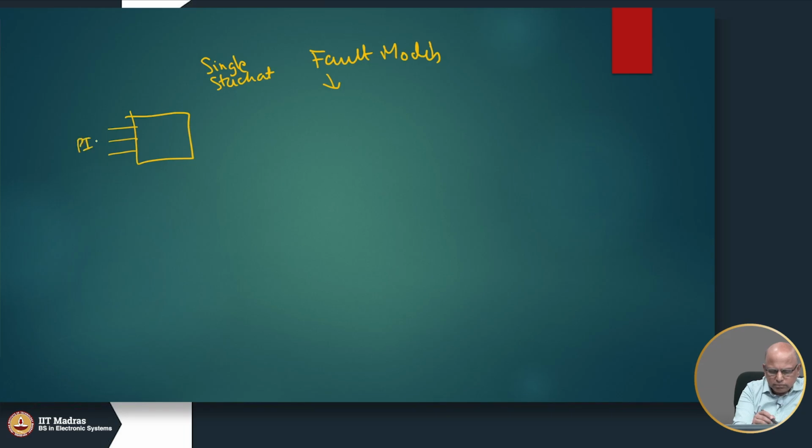So, we have been talking about fault models. In particular, we talked about the single stuck-at fault model, and how for combinational logic we can use the fault compaction theorem to eliminate equivalent faults and dominant faults. The theorem says that if you give me a combinational logic with some primary inputs and there are some fan out branches inside.